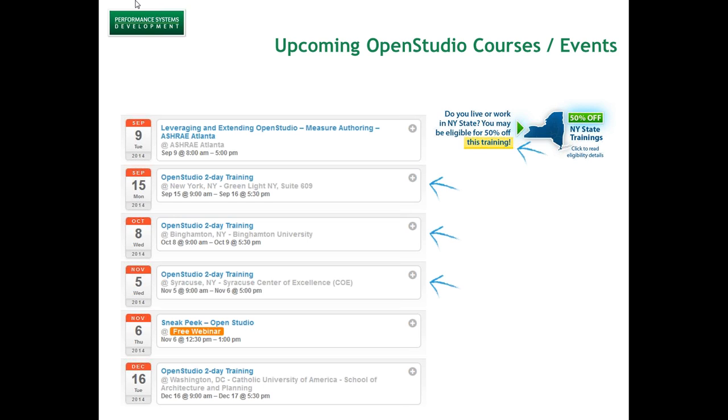Another very unique feature of OpenStudio is a feature called Apply Measure Now. We'll talk about measures themselves in a few slides further, but suffice it for now, and I'll demonstrate this, Apply Measure Now is a way to automatically or programmatically inject what's called a measure into your OpenStudio model.